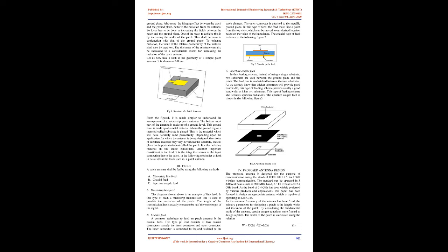In order to obtain and satisfy various properties and radiation characteristics, the shape and the structure of the patch can be varied or modified. Shapes such as square, rectangle, circle, ellipse, etc. are some of the shapes that can be used for the patch. Speaking about performance and radiation characteristics of the antenna, the dimensions of the patch, substrate, and the ground plane play a major role. Starting with the patch, if it is rectangular or square, then the length, width, and thickness of the patch play a key role. If the patch is circular or semicircular, then the radius of the patch plays a major role in determining the behavior of the antenna.